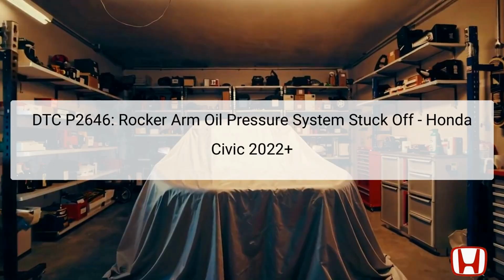The Diagnostic Trouble Code, DTC P2646, is triggered when there is a malfunction in the rocker arm oil pressure system in the Honda Civic models from 2022 and onwards. This specific code indicates that the oil pressure system for the rocker arms is stuck off, meaning that the output from the rocker arm oil pressure sensor remains low despite the rocker arm oil control solenoid being active.